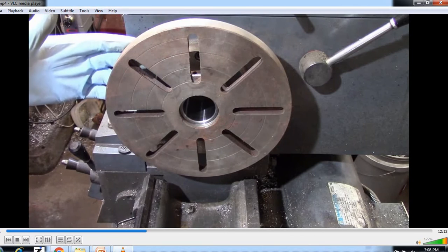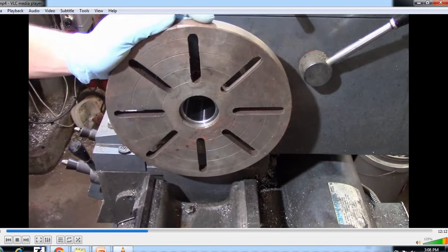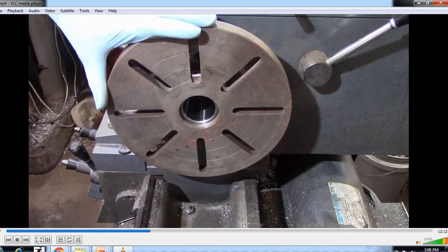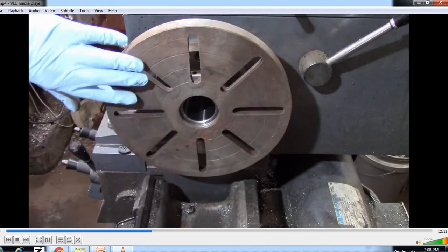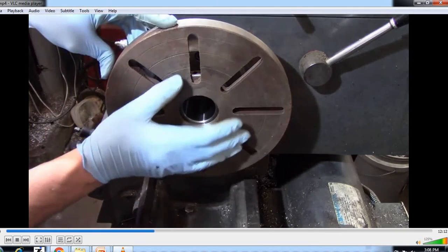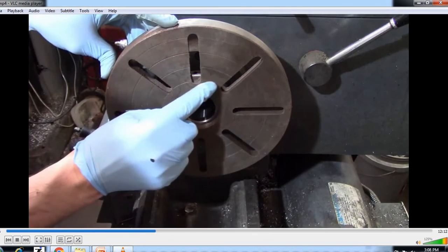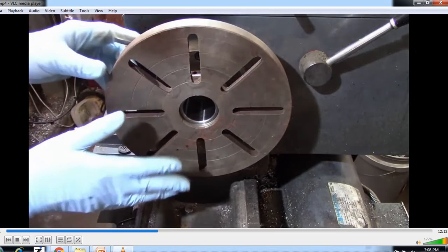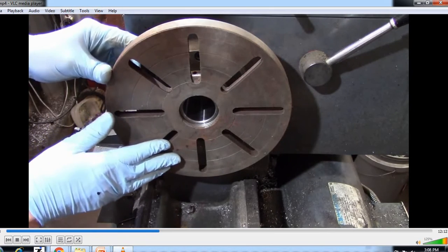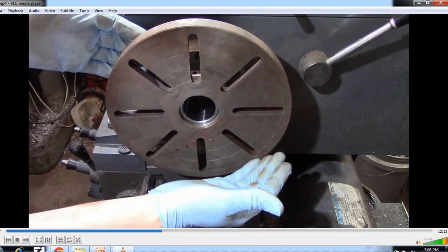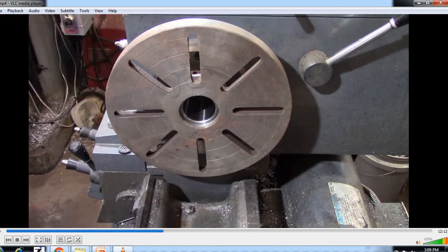In addition to these work holding methods, one can also bolt large irregular workpieces like castings and forgings directly to a faceplate, which is a flat plate with slots for mounting bolts. When placing your part on the faceplate, you get it roughly centered using the concentric rings machined into the face. Faceplate work is generally off balance when the lathe is running, so care should be taken to either place counterweights on the opposite side of the faceplate to balance the load, or just run the lathe slowly.